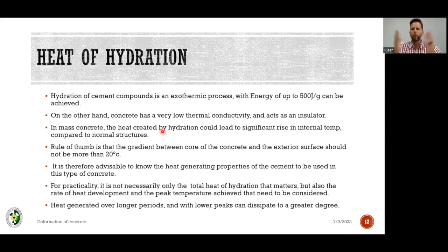So it's unfortunately also random. So you might not be able to establish between ASR and heat of hydration if you look at these cracks, especially if there's no white substance leaching from the one. So it might even look like an ASR type of crack. It's everywhere. And it's quite disconcerting. The cracks will open up, and eventually the cracks will close up again, but they will still be visible. And because it's cracked, that opening is still there. So you will still have the possibility of moisture ingress inside your concrete that can bring in stuff, the baddies, into your concrete. We'll chat about the baddies later. That is part of the chemical thing.